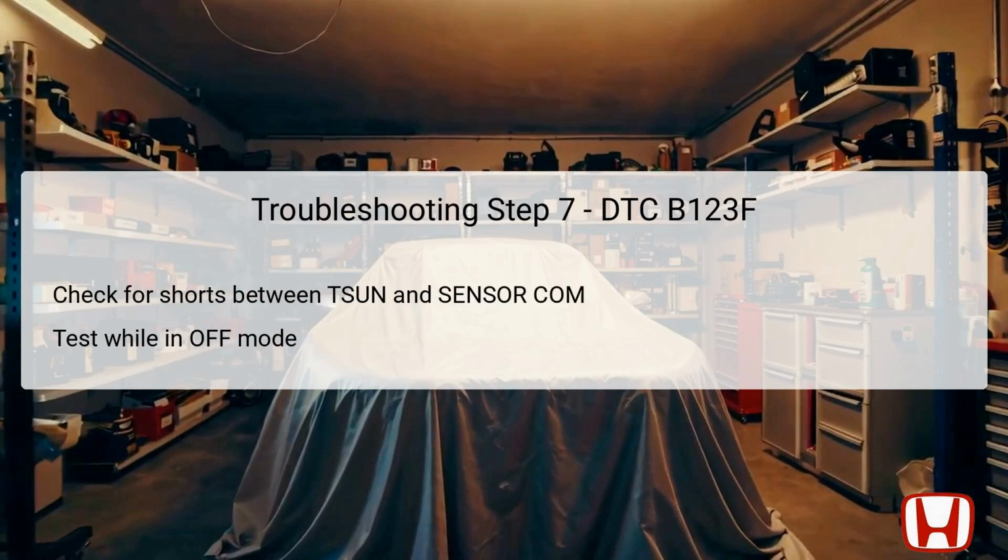Proceeding to step 7, this troubleshooting task involves checking for shorts between the T-Sun line and the sensor COM line. As always, ensure that the vehicle is in off-lock mode, with both the climate control unit connector A, 32P, and sunlight sensor 2P connector disconnected. The focus is on continuity between test point 1, placed at climate control unit connector A, 32P, number 10, and test point 2, found at climate control unit connector A, 32P, number 12.